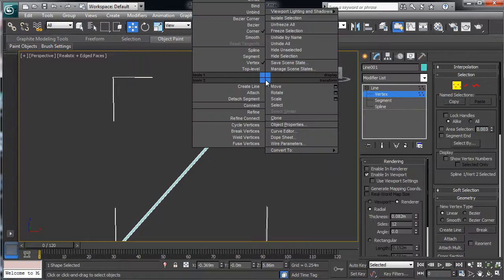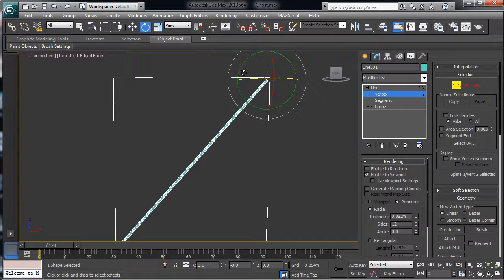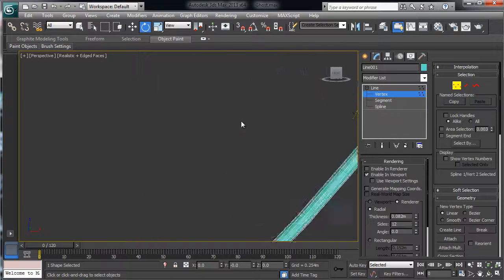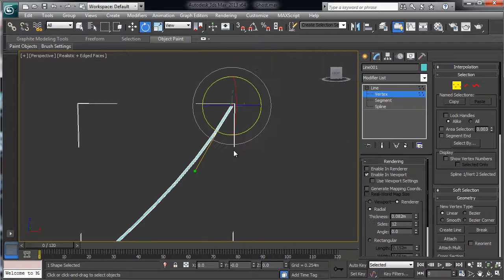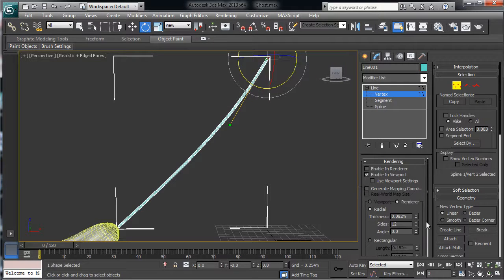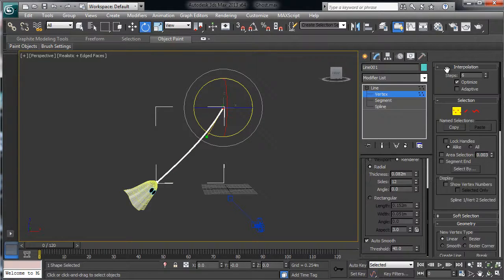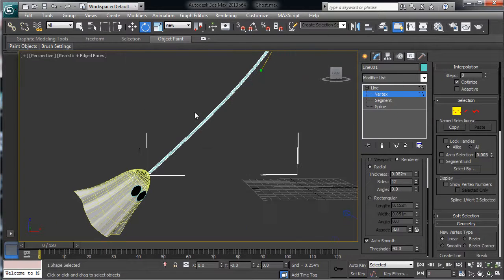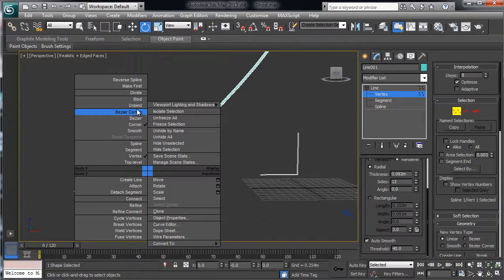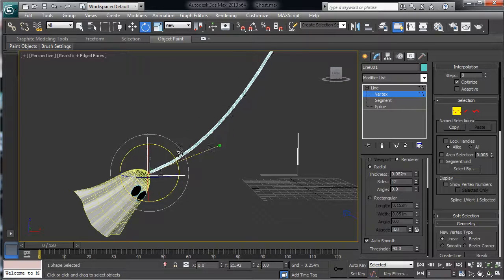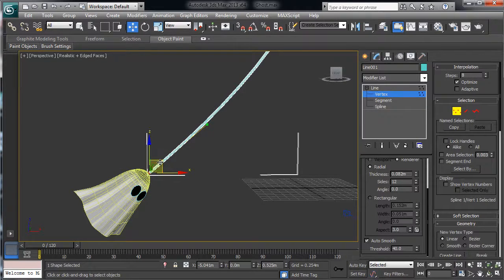So we'll right click on the vertex and set to Bezier. At this point, once we rotate, you'll see that we're getting a few divisions here to help with the geometry. We'll increase that a little bit so that we don't see any kind of breaks in the cord. We're looking for interpolation, and we'll just increase that from 6 maybe to 8. We're also going to add a Bezier down to the bottom too, so that we don't get any kinks. We'll just bend that out a little bit so it has some bend to it.